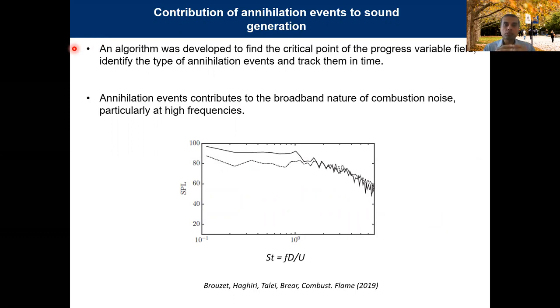That post-processing tool also allowed us to identify the type of annihilation. So we can see, okay, this is a pocket burnout, this is a combination of pocket burnout and pinch-off, and all of those things. The result of that study is presented in a paper that appeared recently. I'm just going to show you one figure from that paper, which is one of the highlights and relevant to today's talk: the contribution of these annihilation events to the overall generated sound, okay? The plot I have here is the sound pressure level as a function of a Strouhal number, which is the non-dimensional frequency, okay?